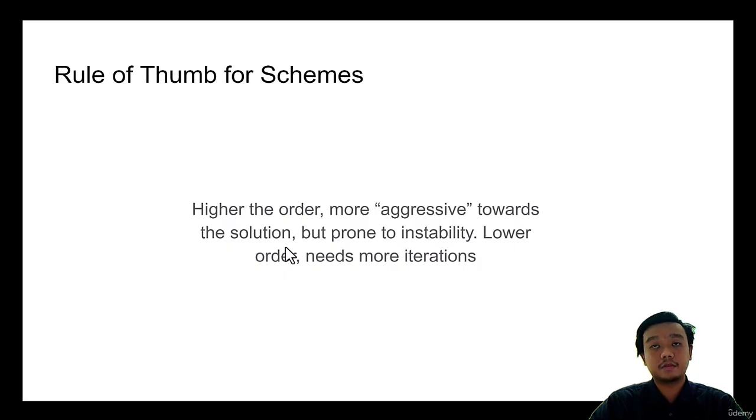For example, if we are simulating a room with a steady state simulation, initialized at 30 degrees Celsius, and we are cooling to 25, it may take about 100 iterations to fully resolve the temperature distribution using a higher order. If we reduce our order, it may take 200 or maybe 300 iterations, but it will be more stable. Yeah, that's the trade-off of scheme selection.